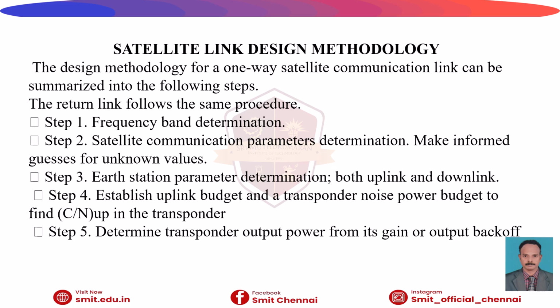So what is output backoff? Generally the satellite amplifiers are non-linear at higher power levels. This is called output back-off. To avoid distortion, the engineers reduce the operating power slightly. This reduction is called output back-off, which is very crucial in satellite design.